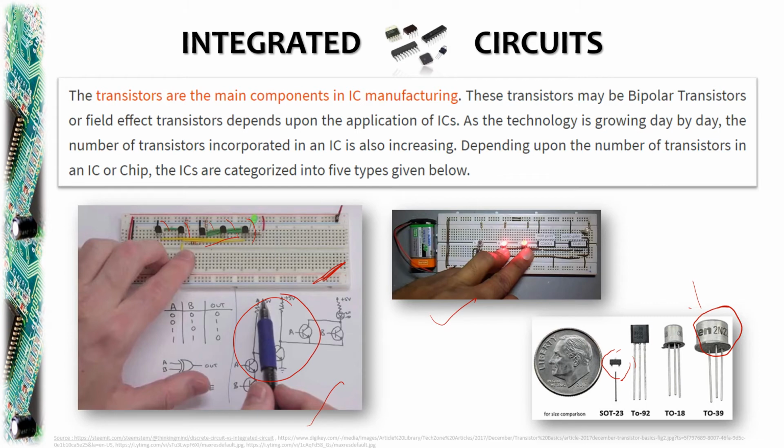Because first you will draw the gate, then you will draw the truth table, then you will draw the circuit diagram, and then based on your circuit diagram you can implant all the components on the breadboard, then attach the battery to it, and test whether it is working or not. So this is just a basic idea of how you can make a gate.